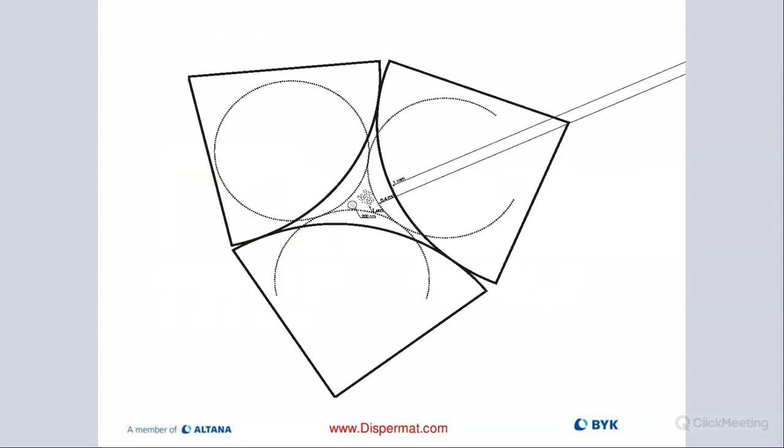On this slide, we're illustrating in another way what happens inside of the mill. You have these larger circles, which are your beads, your 3 beads. The breaking up of these van der Waals forces happens when the beads collide right in the corner there. You see that smaller particle cluster on the left in between those 2 beads, and then it gets pushed away, and the particles are reduced to the smaller particles that you see floating around.